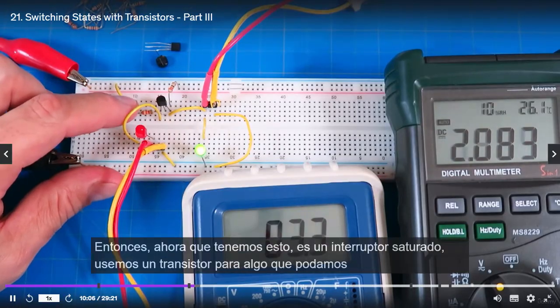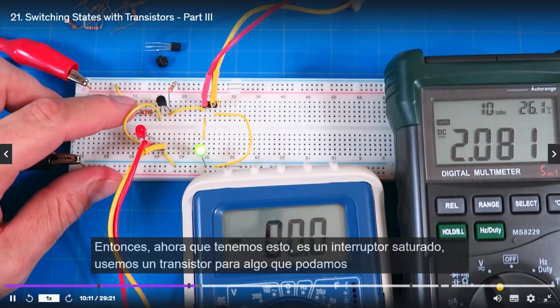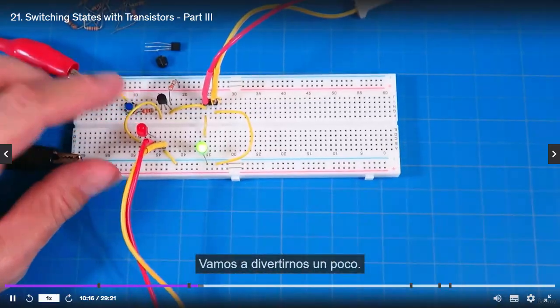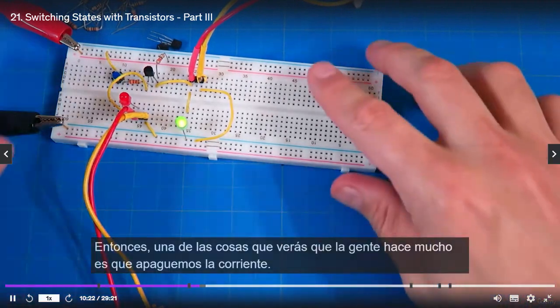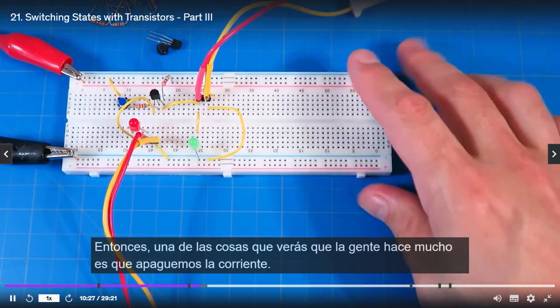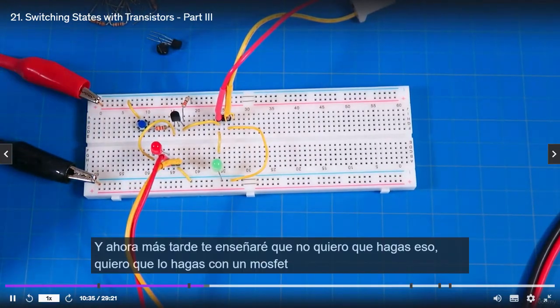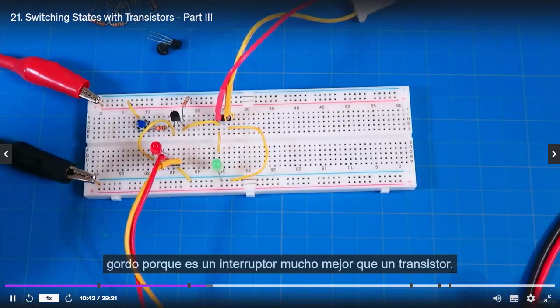Okay, so very cool. Now that we've got this thing as a saturated switch, let's use a transistor for something we might use it for. And again, we're getting ahead of ourselves, but who cares? This is fun. We've been doing a lot of theory, so let's just build stuff. One of the things you'll see people do a lot, and let's turn the power off, is use transistors to drive larger loads, like a motor or something like that. Later I'll teach you that I don't want you to do that. I want you to do it with a MOSFET, because it's a much better switch than a transistor. But for now, we can do that.